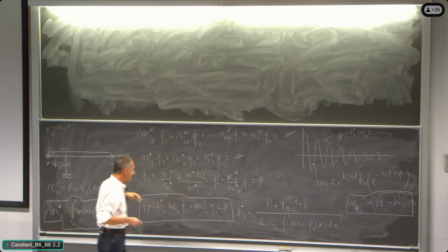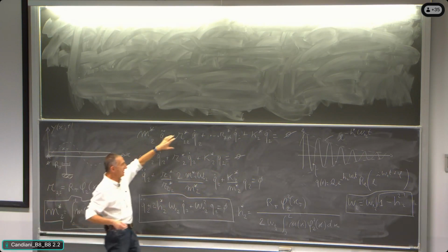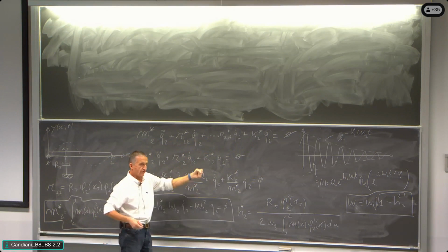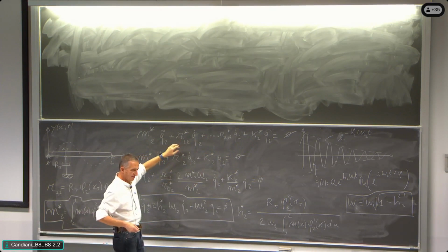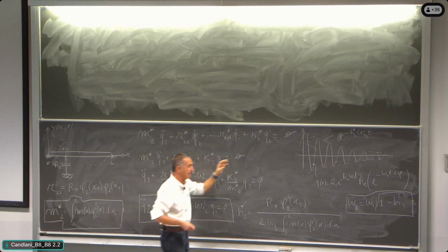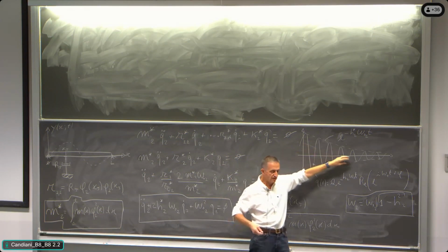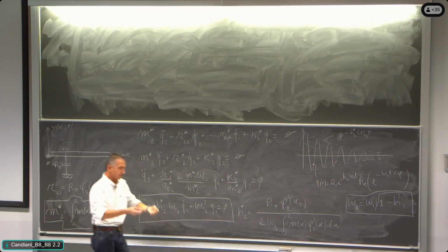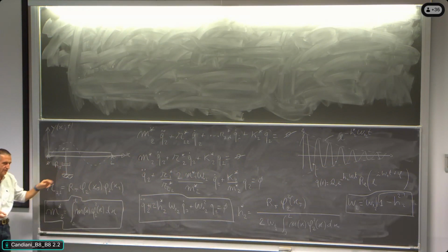Now we know that adding this damper, we are building here a set of quantities that are associated, for sure, to the mode 2, with a specific damping for the mode 2 that is increasing the intrinsic non-dimensional damping of the mode 2, and so we will look at, for the mode 2, a damped behavior like that, all right? So for sure we are expecting that because of the addition of this damper, the mode 2, on which we are focusing, is going to be dampened, all right?